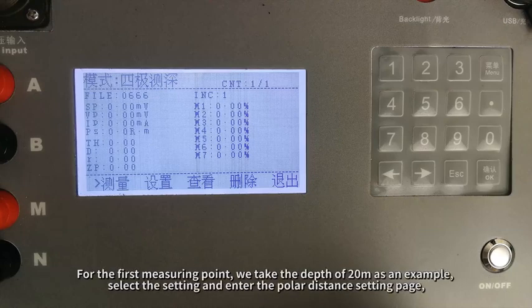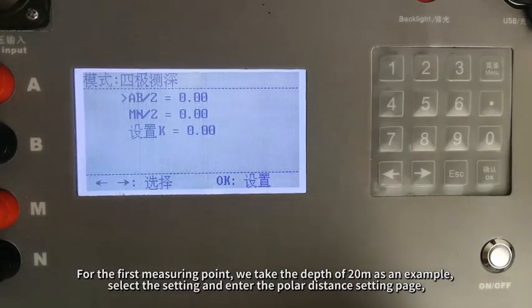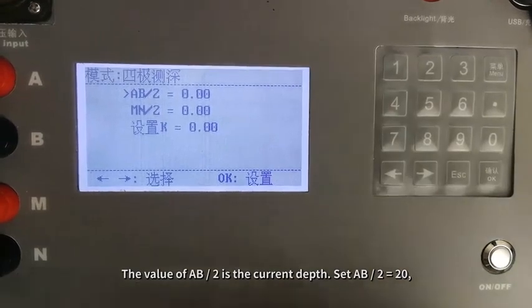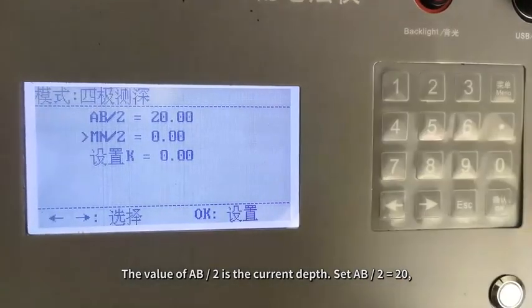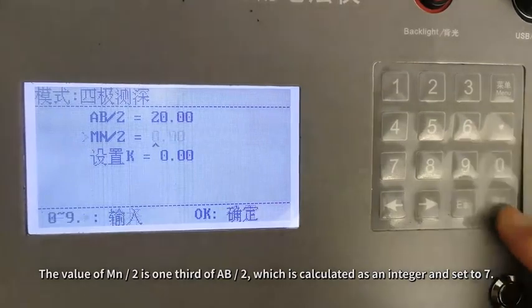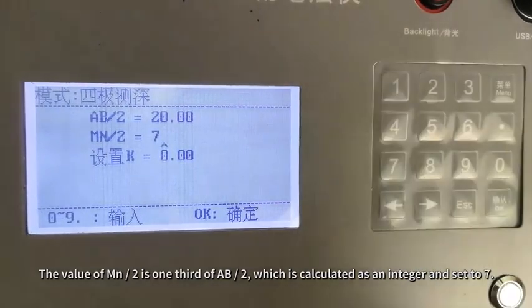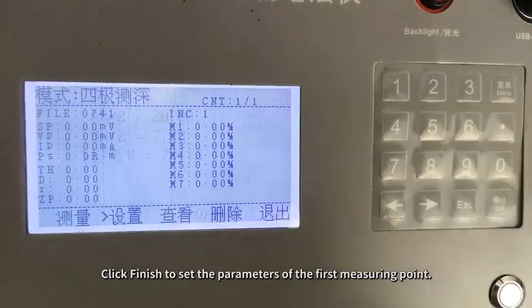For the first measuring point, we take the depth of 20 m as an example. Select the setting and enter the polar distance setting page. The value of AB/2 is the current depth. Set AB/2 equals 20. The value of MN/2 is 1/3 of AB/2, which is calculated as an integer and set to 7. Click Finish to set the parameters of the first measuring point.